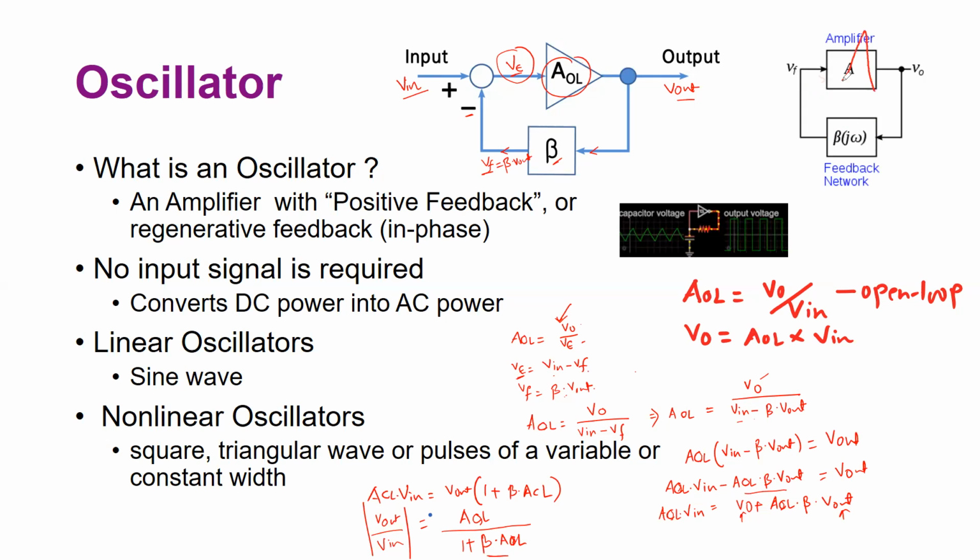Again, it is amplified by this amplifier. Again, that comes out as an input along with the other frequencies, and the filter here will again select only that signal frequency. The magnitude of the oscillation will keep on increasing. That's how you start with a lower magnitude of oscillation and reach sustained oscillation. There is a constant oscillation established. That is how your oscillator will work.